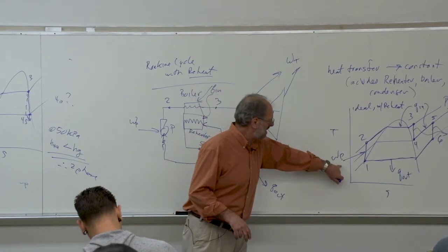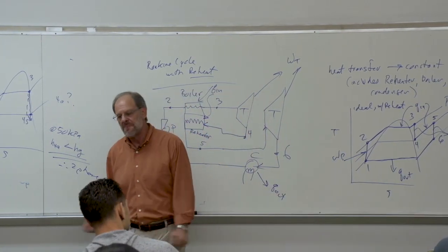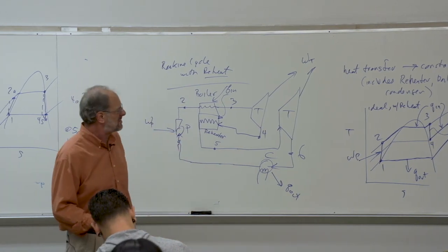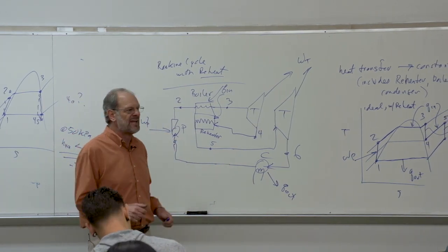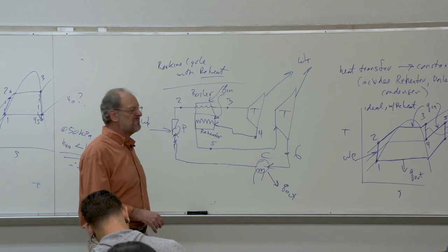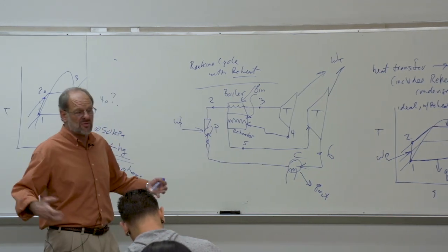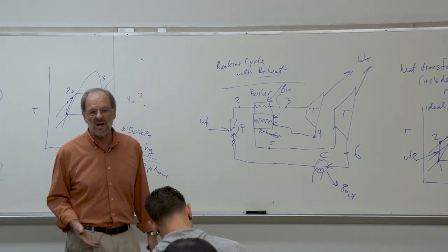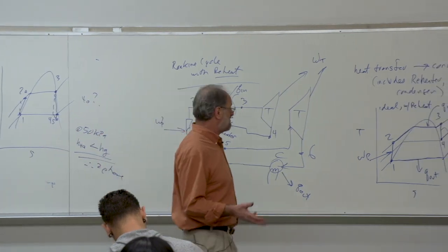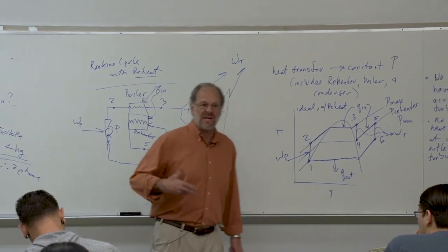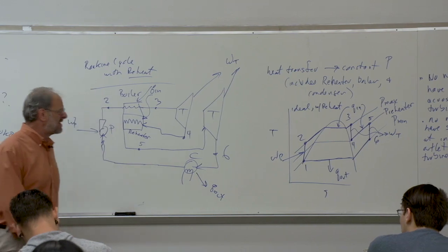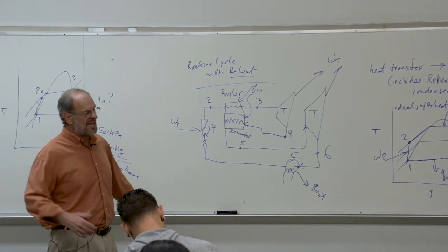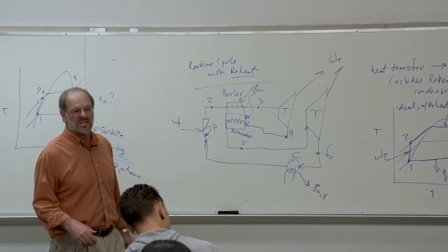Turns out that pumps are really the biggest maintenance issue. Rotating equipment in general tends to be the biggest maintenance issue in a power plant. So, having multiple pumps that operate at fractional capacities is good from a maintenance point of view. Yeah, it costs you more money, but it would eliminate downtime, and therefore you're still able to make more money than the extra money it costs you to buy the extra pump. Again, things to think about in the wonderful world of thermodynamics.